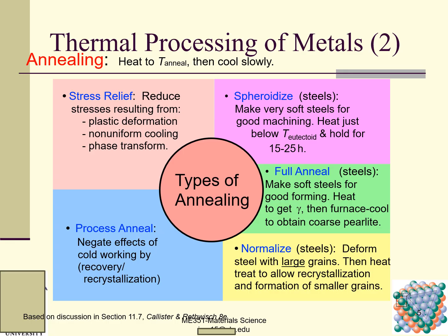Then we have normalizing, also for steel, with deformed steel with large grains. We heat treat to allow recrystallization and formation of smaller grains. Normalization results in smaller grains, which consequently results in a stronger material.